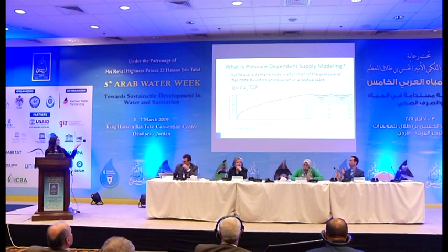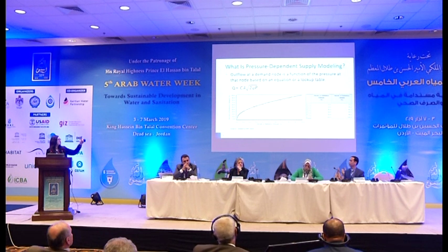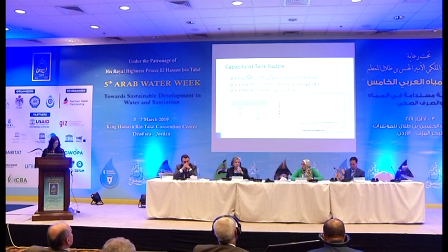There is a reference pressure, which is the pressure that gives the exact demand at this point, and the percentage of the pressure available at the node is related to the percentage of the demand that the customer can achieve based on that pressure. The tabular format just shows this curve as numbers.